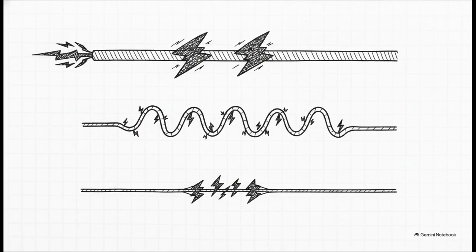The brutal physical reality of a metal wire on a silicon chip is that it is absolutely not a zero-resistance path. If we look at the basic equation for resistance, resistivity times length divided by cross-sectional area, it tells us a really clear story. Longer wires inherently resist the flow of electricity more, and narrower wires, they spike the resistance even further. In modern chip design, this is a massive headache. Why? Because we are packing billions of transistors closer together, which means wires are getting microscopically narrow and surprisingly long.